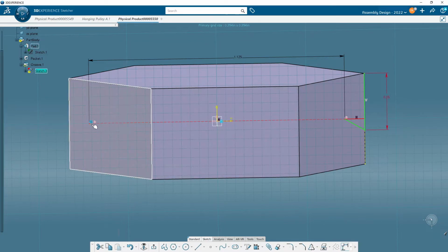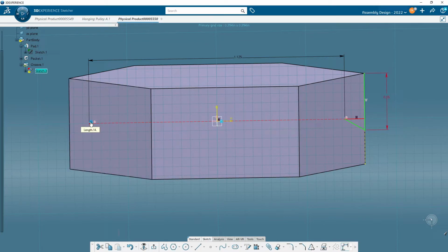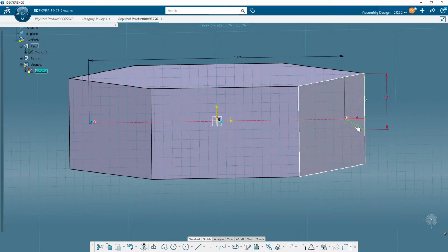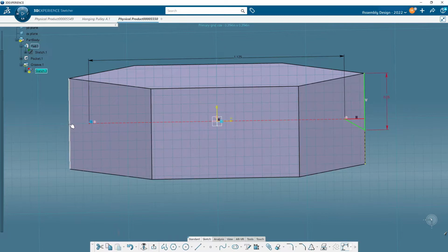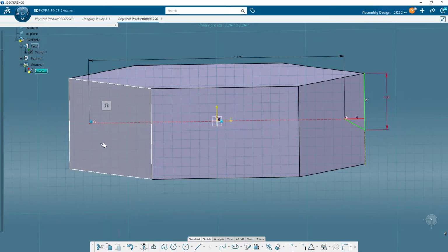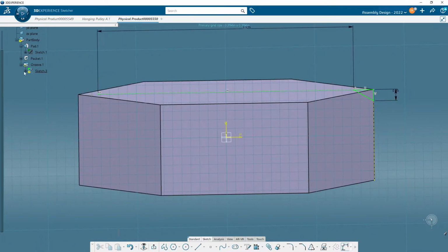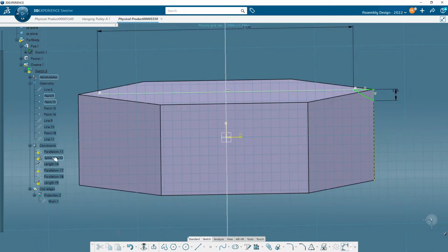So in this particular case, when I delete that constraint right there, that coincident constraint holding it on the horizontal, this line and everything immediately jumps right back up to there. So I'm going to do that again. And all is green again. And if we open up our sketch and we look through here, a lot of the stuff is gone.